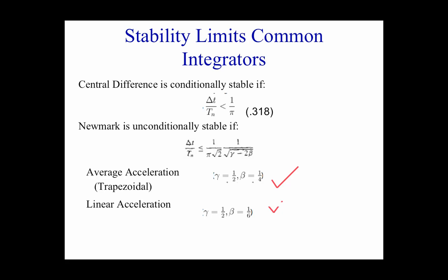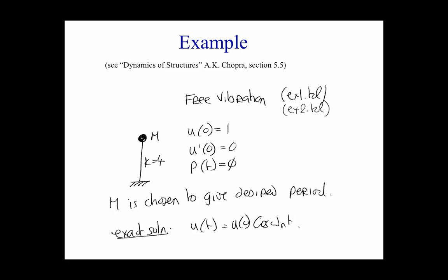And remember, in a nonlinear system, it's not that initial stiffness period you have to worry about. It's sort of further on down the line when the system starts going nonlinear. What is that period? They're the periods you have to worry about. And I'll give you some little examples, sort of showing you what picking the different periods, the different time steps, can be.